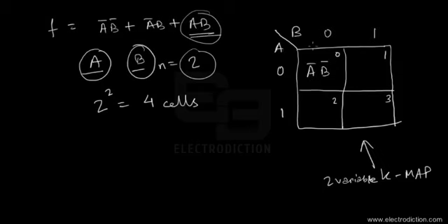So here you can see that in this particular cell the values of a and b are both zeros. For an SOP format of representation, 0 means a complemented variable. Okay, so we can write down the minterm for both the variables a, b, that should look something like this: a bar b bar.